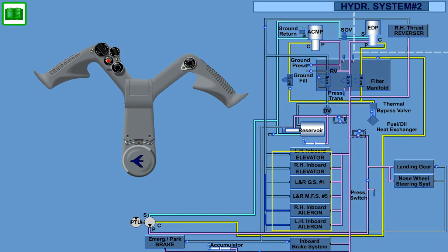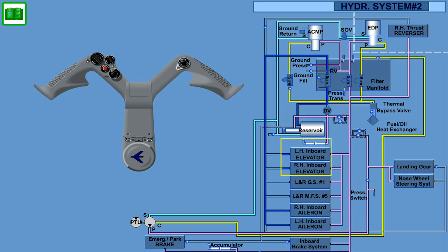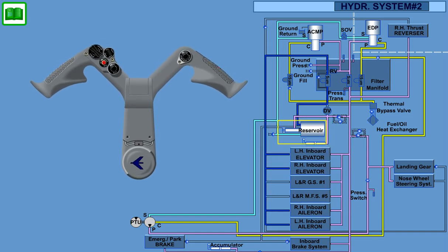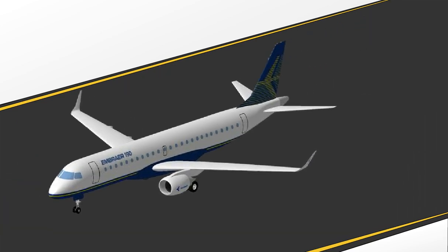Some cycling of the hydraulic system users is also required to ensure that cold hydraulic fluid has been displaced from their circuits. Once the warm-up procedures are complete and the hydraulic system parameters have reached their minimum operating limits, the aircraft is ready to taxi.